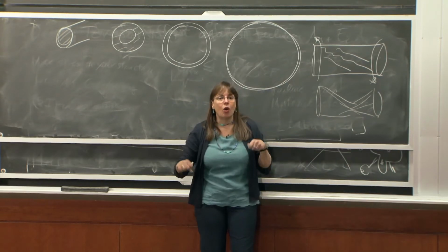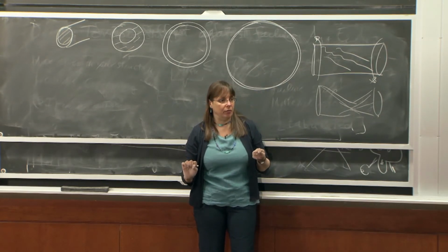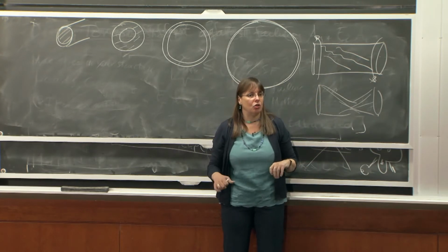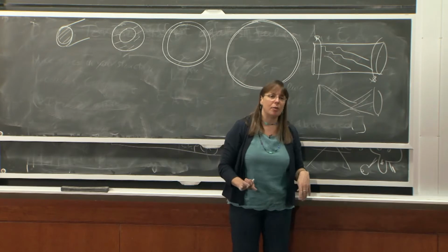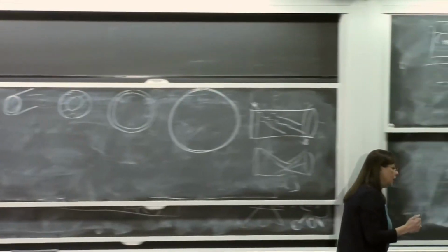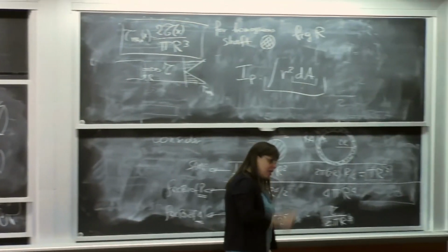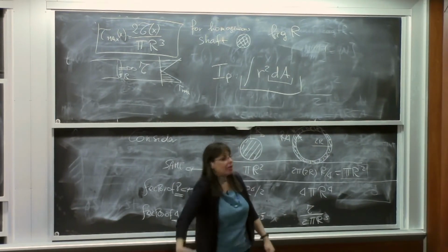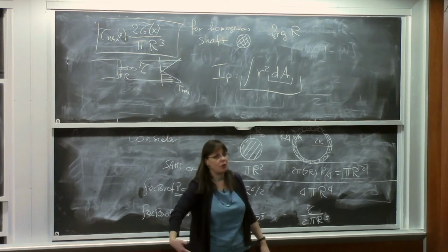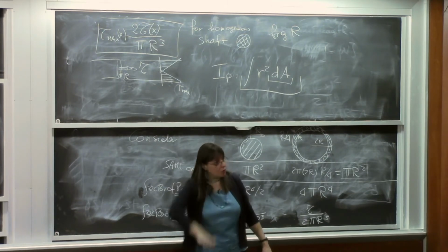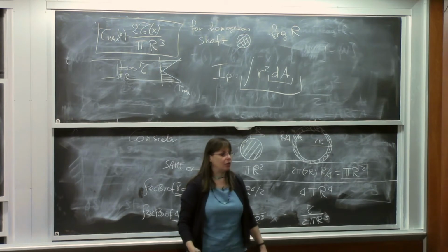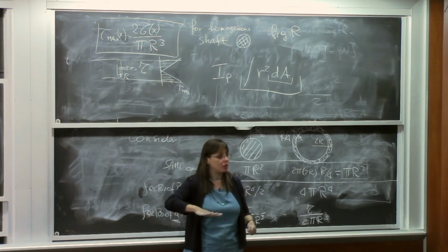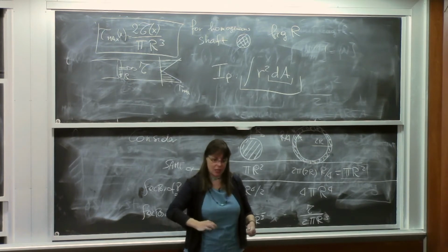You do not want a structure to do that. Why do you think it does that? You're twisting it. We talked about buckling before. Remember, I said if you have a thin, slender bar and you put it in compression, it buckles out of plane, because it says, I don't want to be straight. I can accommodate this load by bending around instead of being compressed axially. That's a buckling load.